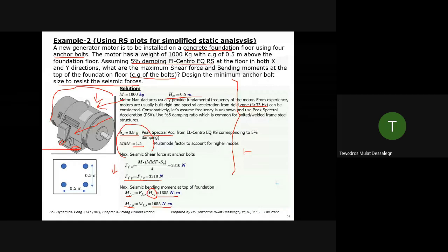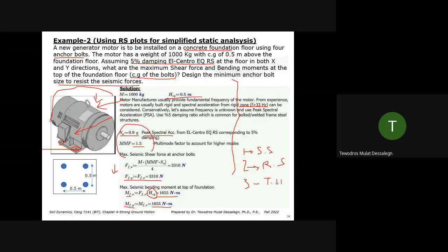That's called pseudo-static analysis. Or the second one is you can do response spectrum analysis. You can put the response spectrum plot for SAP or STAAD.Pro, and they will analyze it. And the third one is you can use your time history. It's very time-taking, but more realistic.